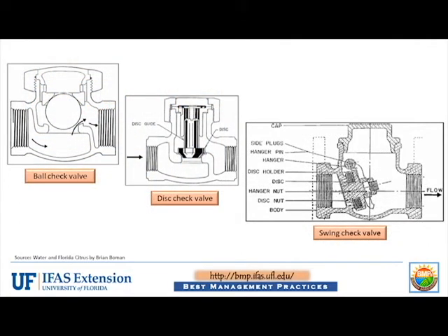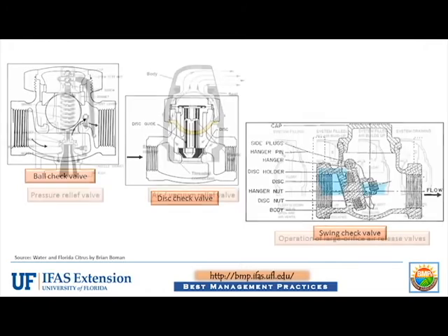Check valves. A functional check valve located in the irrigation supply line between the irrigation pump and the point of injection of a chemical is required. The check valve will prevent water from flowing from a high elevation or pressure in the irrigation system back to the well or surface water supply. It will also prevent water from being siphoned back to the water source. Thus, water with chemicals cannot flow back into the water supply.